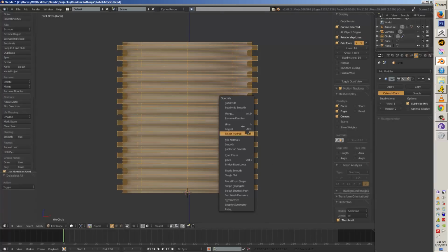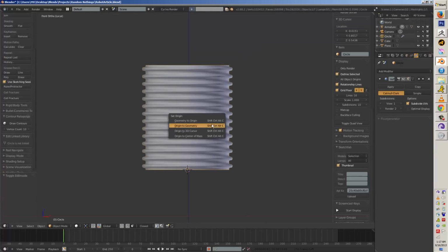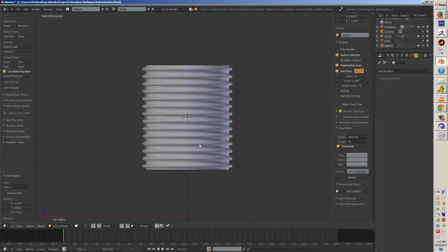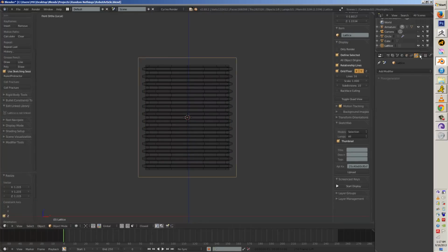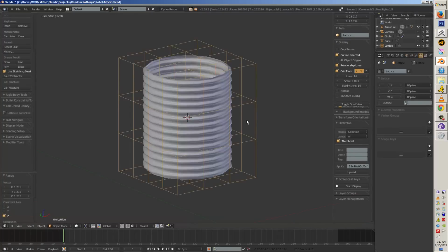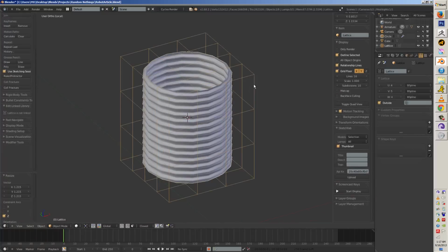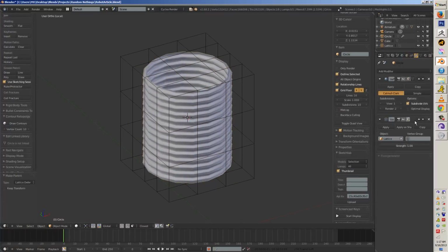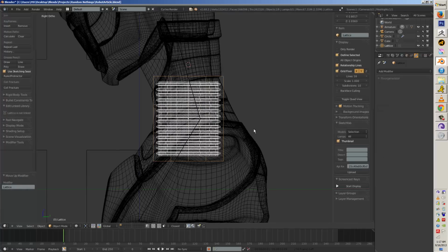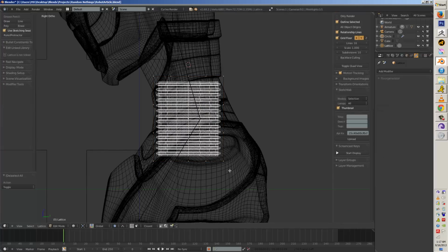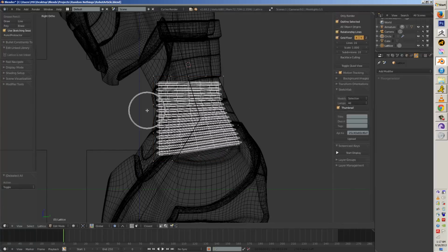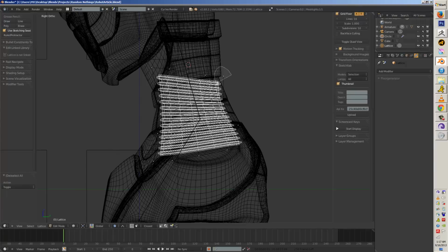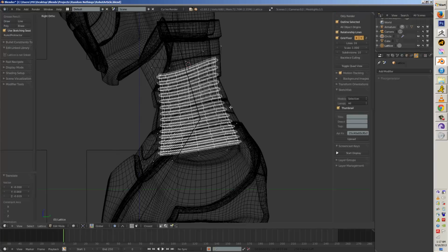So you'll see me apply the array after turning on merge, setting the cursor to the geometry, adding in a lattice, adding some spans, changing it to be outside only, Control P, parent, go to my object, remove that lattice parent so I can delete it freely without it making my geometry jump. And now I can just freely world deform, shape this in there.